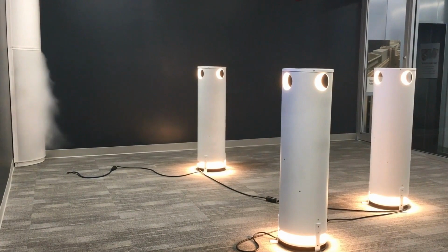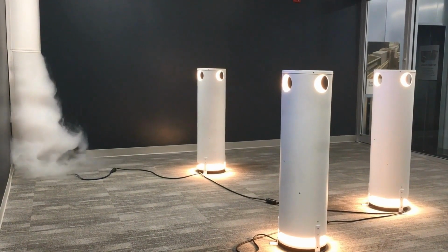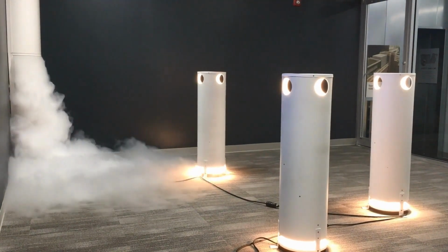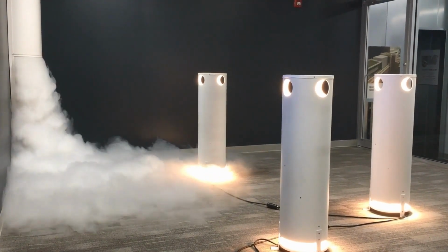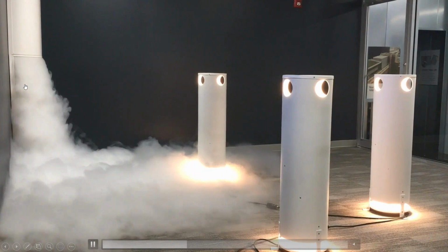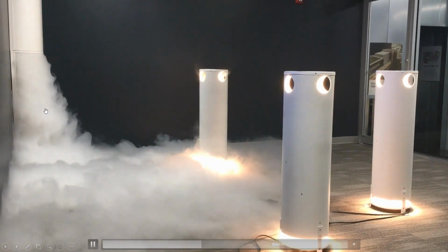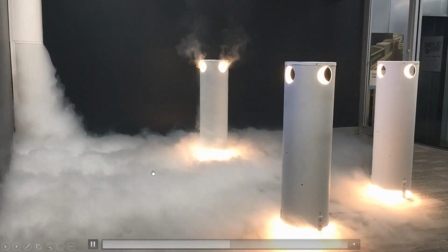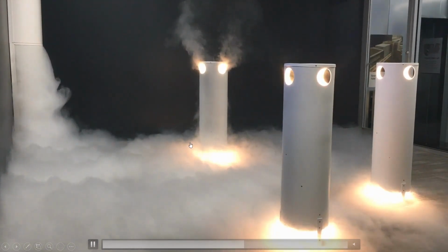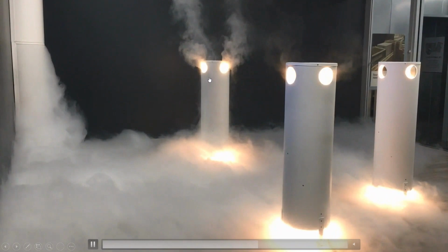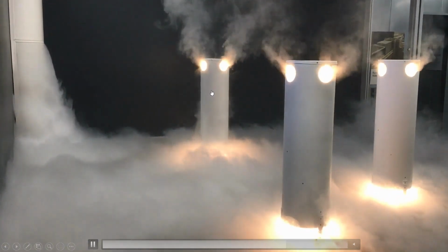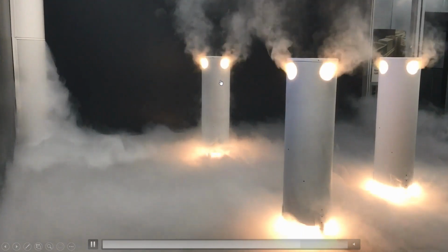So to give you an example of what that looks like, this is an example in the tech center down here in Suwanee, Georgia, where I'm located, and you can see we've got the air coming out around 40 feet per minute, and it immediately is dropping due to the buoyancy difference. And from there, it's being immediately sucked out or pulled across the room, not thrown, by the heat sources themselves.